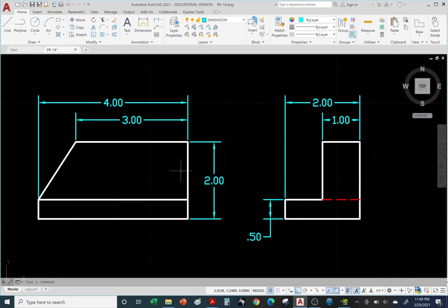Obviously, this is inches. One way you can tell on a drawing whether this is inches or millimeters, how can I tell? Well, you can tell by the small numbers, right? If it's millimeters, you would see 30 millimeters, 50 millimeters. Another way to distinguish from a millimeters drawing is to look at the number smaller than 1.